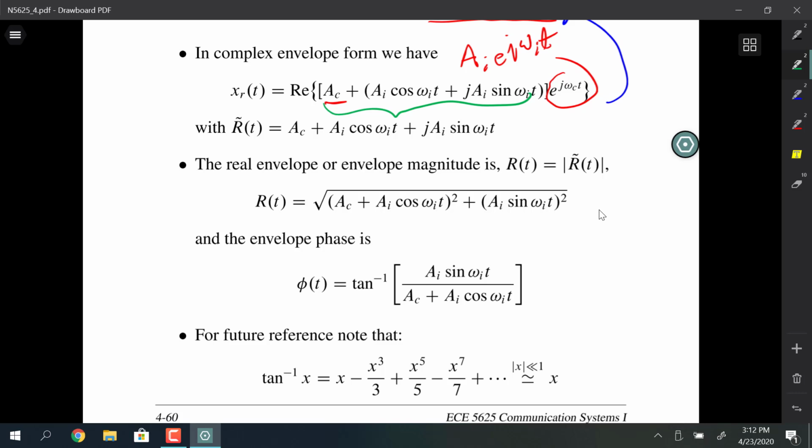We particularly focused on getting the envelope of the complex envelope. But now that we're doing angle modulation, we're not so much interested in that. As a matter of fact, I shouldn't say we don't care about it. What it comes down to, though, is when we were talking about the use of a limiter or clipping circuit in a front end of an FM or angle modulated receiver, that's to remove the envelope fluctuation. So if the envelope fluctuations are mild, we can get rid of those with our limiter.